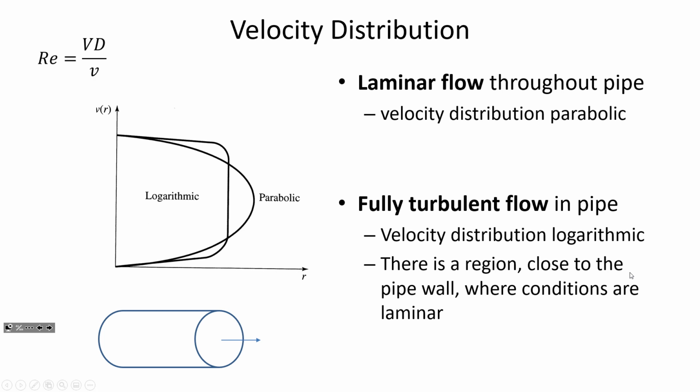So you'll remember back to fluid mechanics when we introduced the idea of a velocity distribution. And let me just refresh your memory that in a flow through a pipe, the velocity of flow is the largest in the center of the pipe. And near the edges, where the water is in contact with the pipe material, the velocity is the lowest. And in fact, if we zoom in on just that molecular layer that's directly adjacent to the stationary surface, that molecule of water that's just right at the border isn't moving at all, because of the no-slip condition,